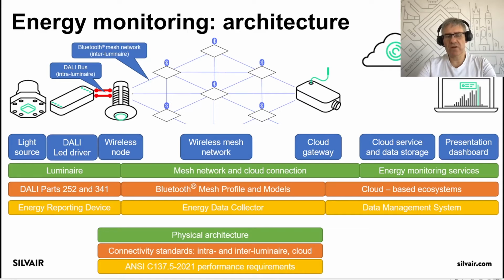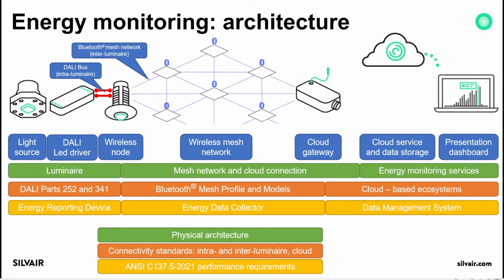It may connect in the end to a device that is a cloud gateway. The function of the cloud gateway is to collect data from the entire mesh network. So each luminaire here reports its own data, and through the mesh network, this data flows to the gateway, and then the cloud gateway forwards this data to a cloud service, which stores the data and provides the source for presentation dashboards.